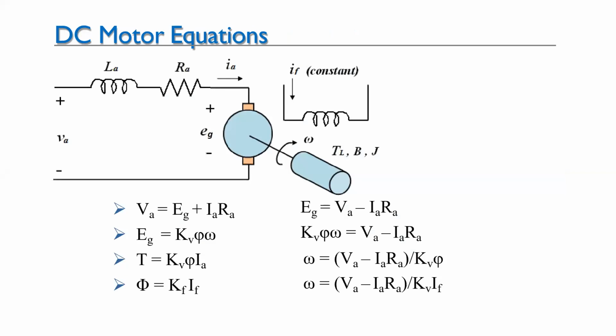So what you have understood in this is that there are 2 windings, or you can say one armature winding is there and another 2 permanent magnets are there. In case of DC motors, where we want to operate a shunt motor, DC shunt motor, series motor, or separately excited DC motor, in these types of DC motors, a field winding is provided. In this picture, one field coil is there and here IF is written. This field winding is serving the purpose of the permanent magnets and the armature coil, which you have seen in the picture.